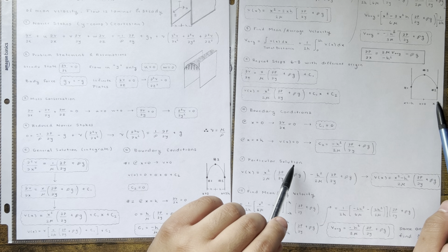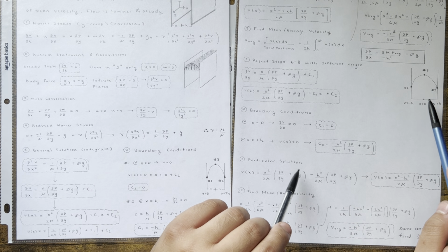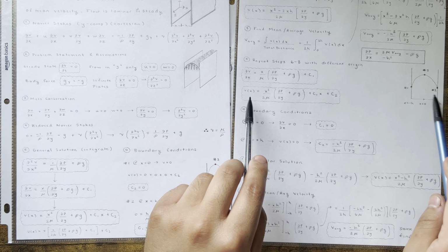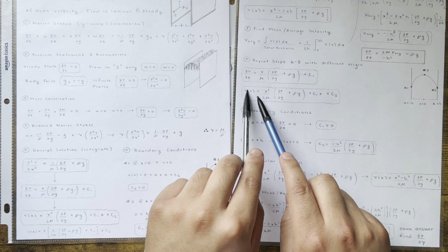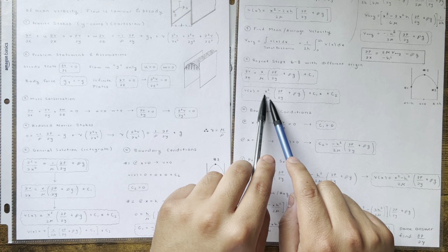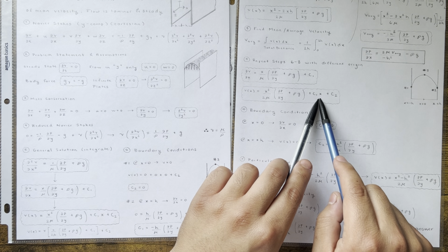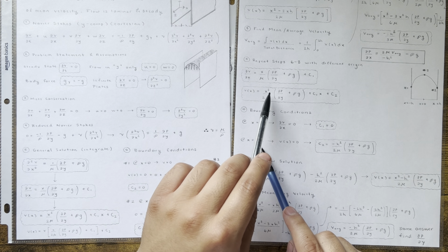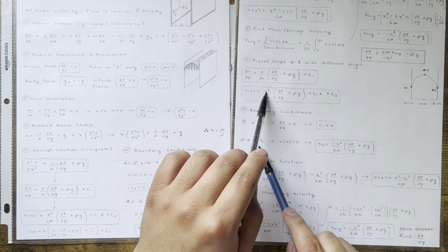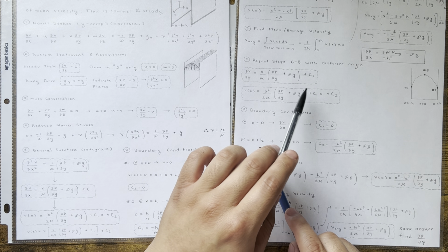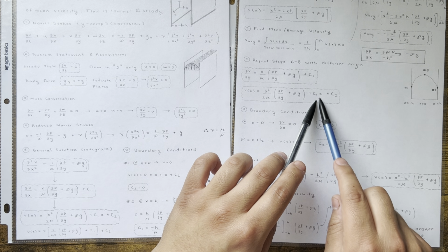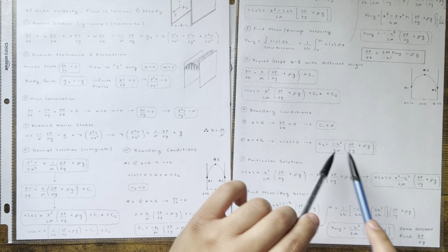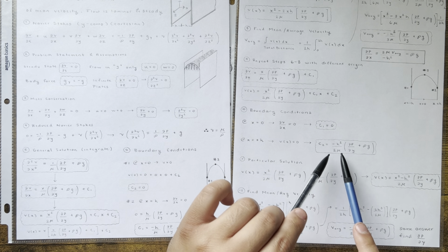Now I could use either or, and then I could say velocity is 0 at that location, okay? So in this case, I chose positive H. When you plug in positive h for your velocity function, you plug in h wherever you see an x. So this becomes h squared over 2 mu, right? Plus c1, well, c1's already 0. So you get h squared over 2 mu plus all this times all this, and then you just move it to the other side and solve for c2. And that's what I did.